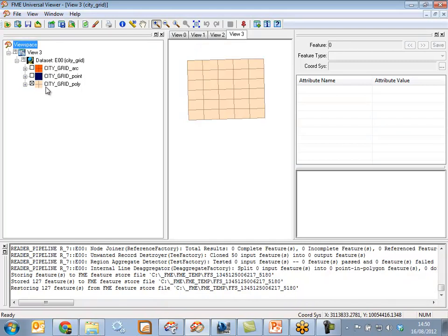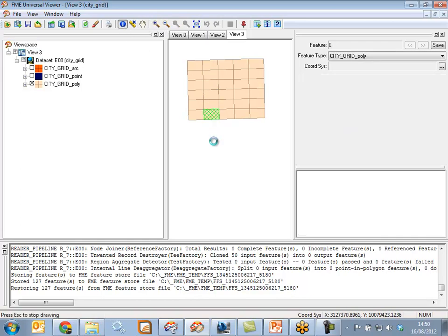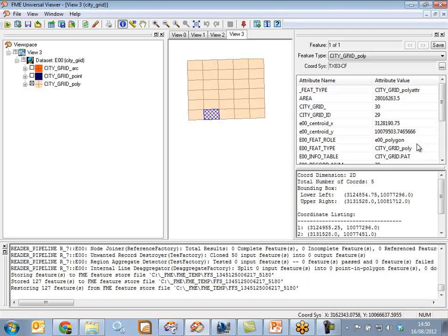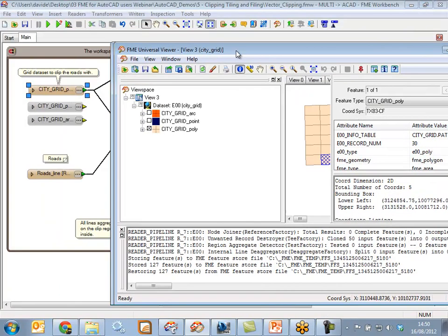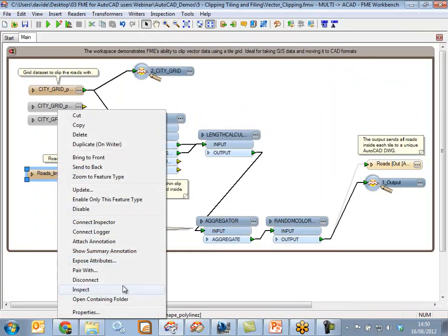There is one layer inside this city grid file, and this is an Esri exchange format. You can see that there are some polygons tucked away in here, and each one of these polygons has a value, and the value here is tile name. In this case L24 is the name that we're going to find useful.